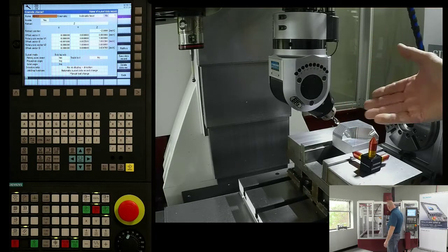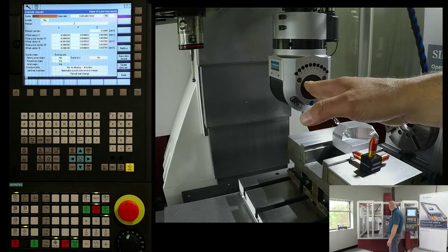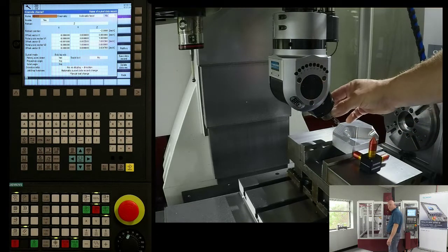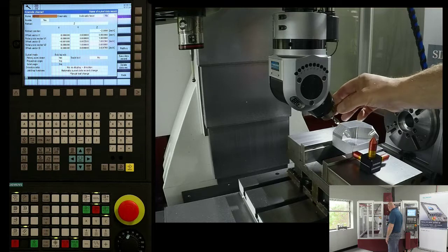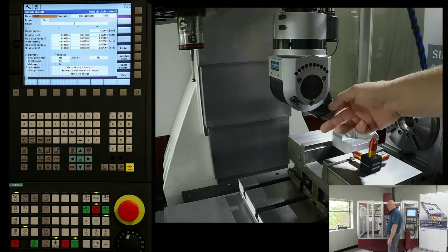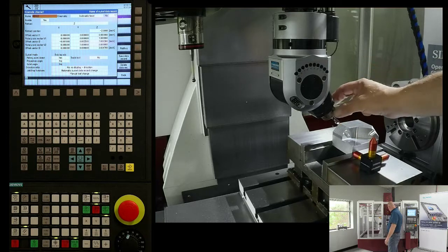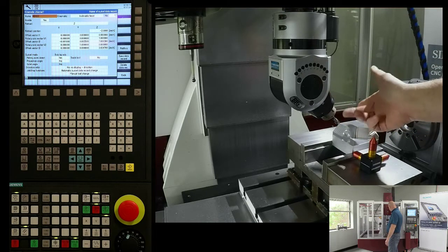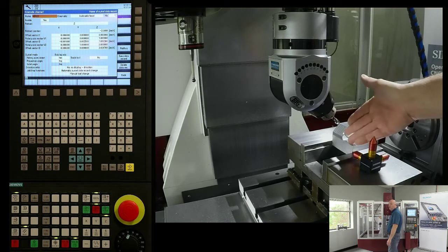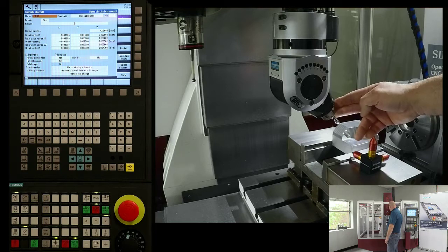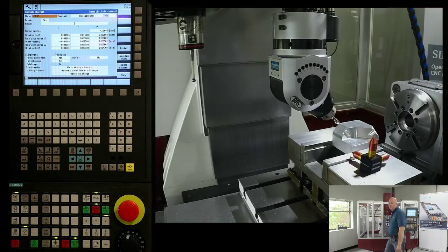So what we're going to do is we're going to establish a value from the center of rotation, and I did it out to my collet face. If you have a quick change holder, some units do, you could have that value to the quick change, and then I could swap these out at will. This one has just an integral collet, so I established it to a collet face. So if I put a stop or something in here, I could change the tools even mid-program or mid-process if I needed to without having to fully retouch all the tools off.